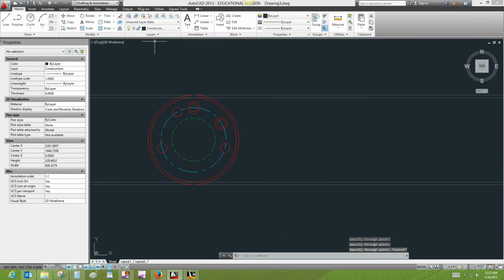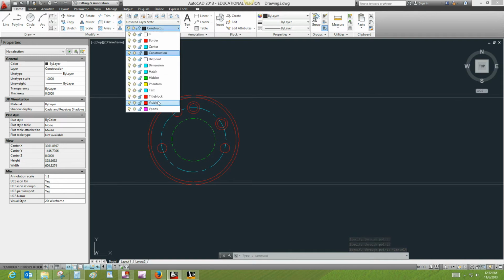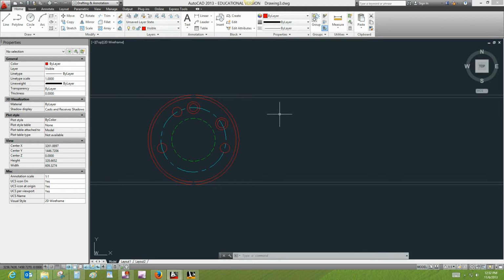Okay, so from there, let's use our visible line. We're not actually given any spacing dimensions between views like we were before. Not an issue though. So let's draw this line straight down. Okay, this is going to be the back of the object. Right now I'm calling this our front view. This will be our back edge. So I want to offset by 38 to the left. Okay, and then I will just go ahead and close the box here.